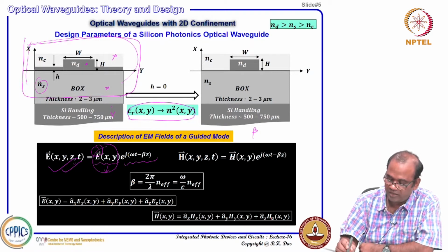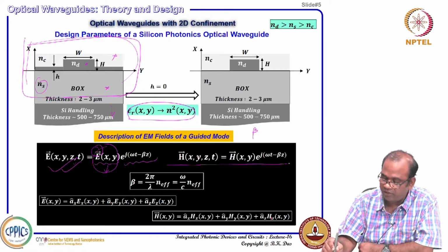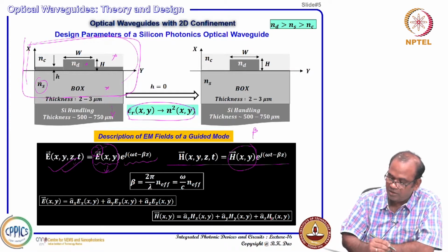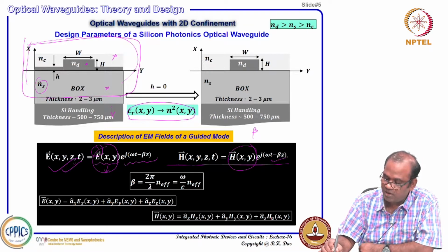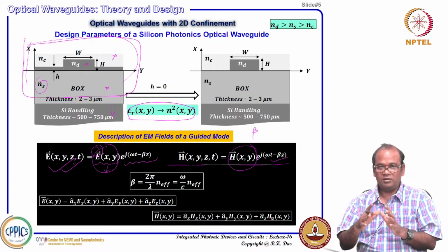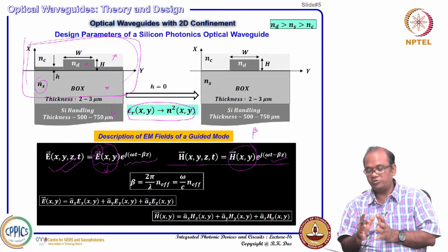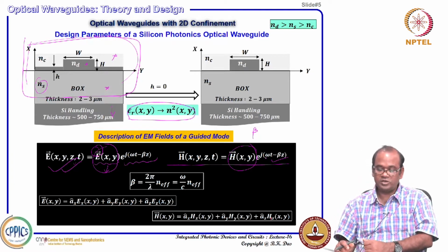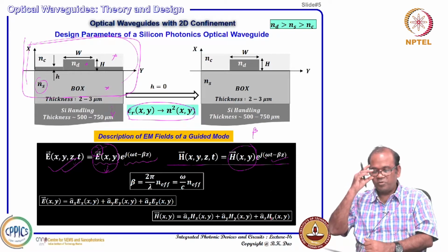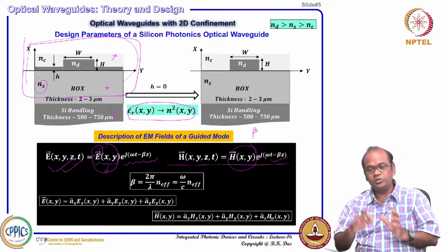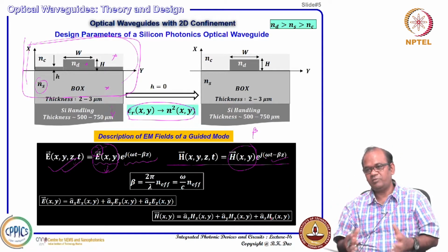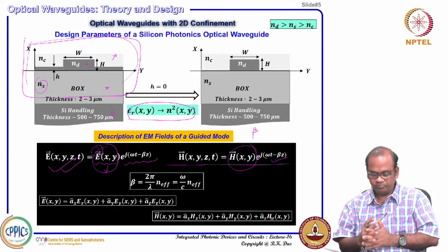You have to consider the magnetic field also. For that particular mode, you will also have a magnetic field with an xy profile vector and also the same phase velocity, because the electromagnetic wave belongs to a particular mode having a propagation constant beta. So, the propagation constant will be shared by both the electric field and magnetic field distributions, because that pattern is called the mode.